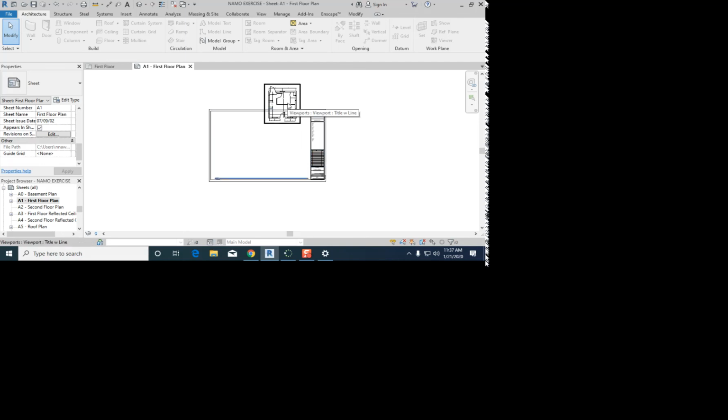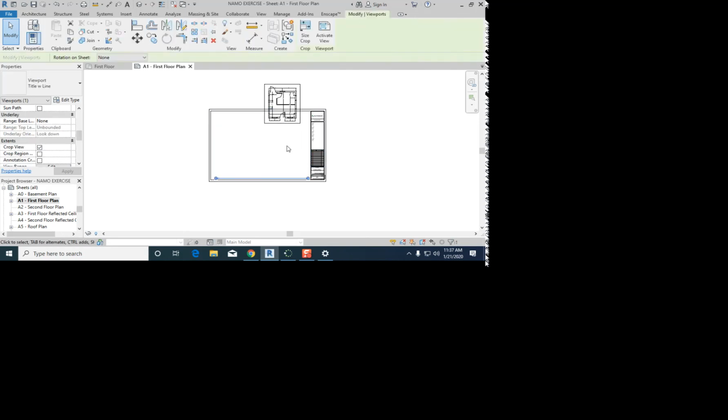Okay. So what I did, I'm gonna hit Control Z. Well, let me just click on it again. Click on your view, and then the first line under graphics is essentially 1/2 inch equals 1 foot in mine. Yours might be 1/4. So go ahead and change it to 1/2. It's a pretty large floor plan, but we've got the real estate.